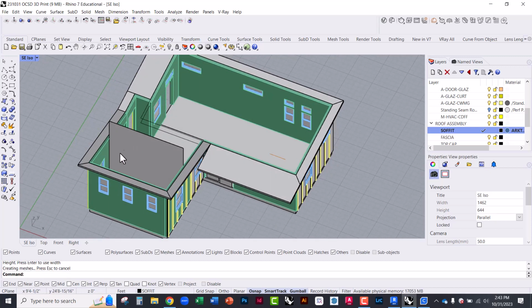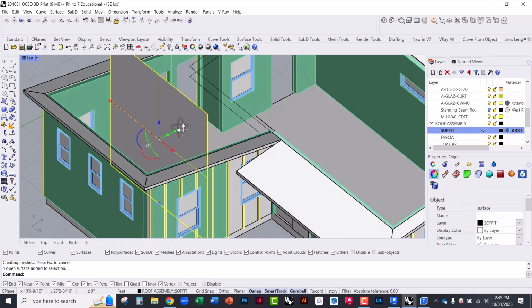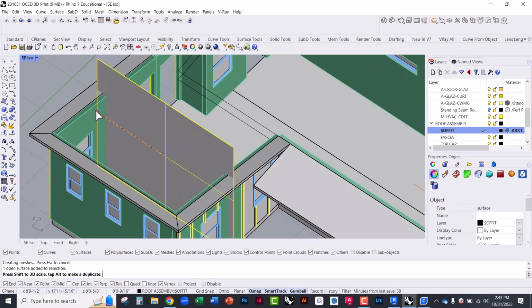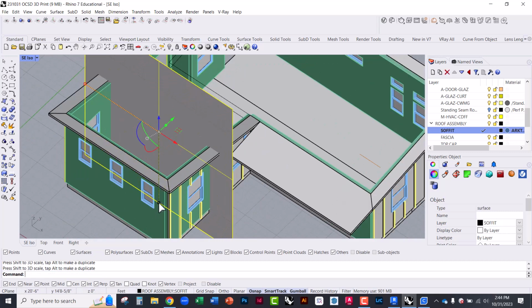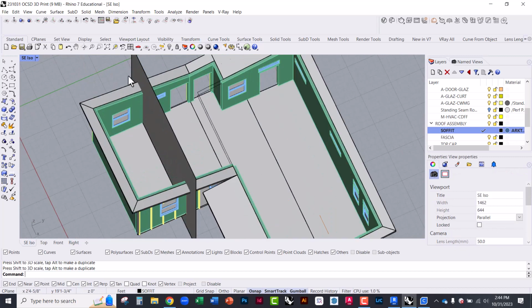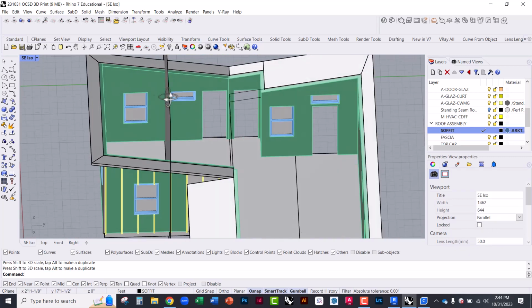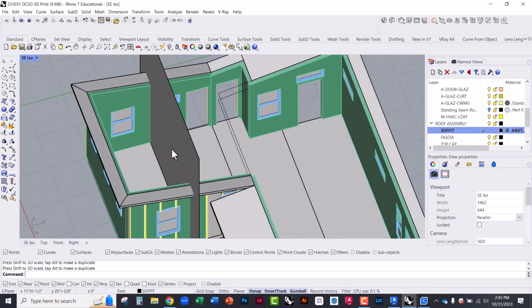So I'm going to create a plane, and I selected vertical before I finished it. So I can click on 2 places, add a vertical height to this, and then selecting this plane, I can stretch it using the gumball tool. So stretch it horizontally, stretch it vertically. And what I want to do here, there's a couple ways I could do this. I could use the split tool. So there's different ways I can split the geometry. I can split it with a surface. I can also do a Boolean subtract.